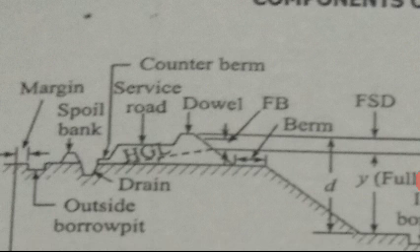Initial aim of this service road is only for inspection and maintenance. Hence, canal roads are usually made up of compacted and dressed earth and are unmetalled and unsurfaced. As such, they can take only very light traffic. However, if a canal road is needed for the use of general public, it should be metalled and surfaced before being allowed for general use.